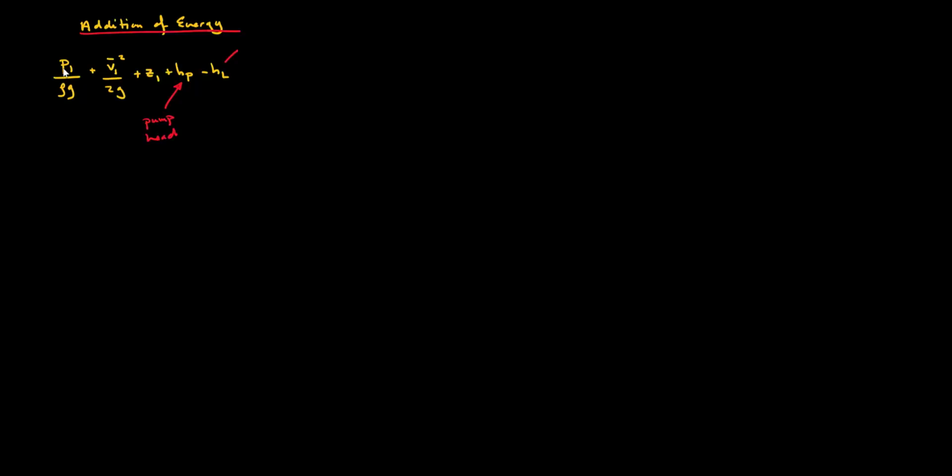And this is our head loss, again due to both major and minor sources over here. And this is finally equal to P2 over rho g plus V2 squared over 2g plus Z2.